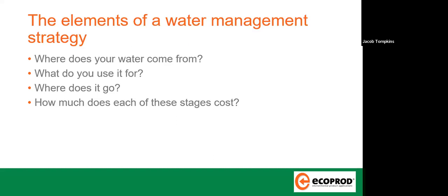So when we talked earlier about intelligent water management systems, that will enable you to target, hang on, this department's using this much water. It will also enable you to benchmark if you've got multiple sites and say, well, hang on, this site for the same allowable lettable area or the same level of production is using twice as much water as this site. Why is that?